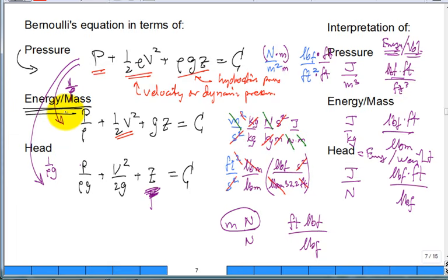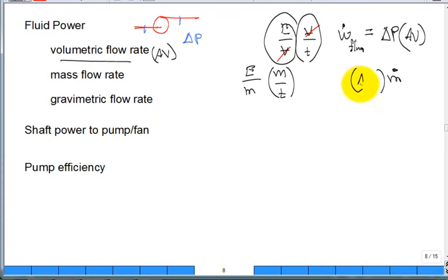Some of those three terms, sometimes they'll have where this is maybe cap H, and this is a lowercase h. Cap H for head, where they mean energy per unit mass, and lowercase h for head, where they mean energy per unit weight. So something changes. Maybe there's a change in the cap H, the energy per unit mass, that would be W dot fluid.